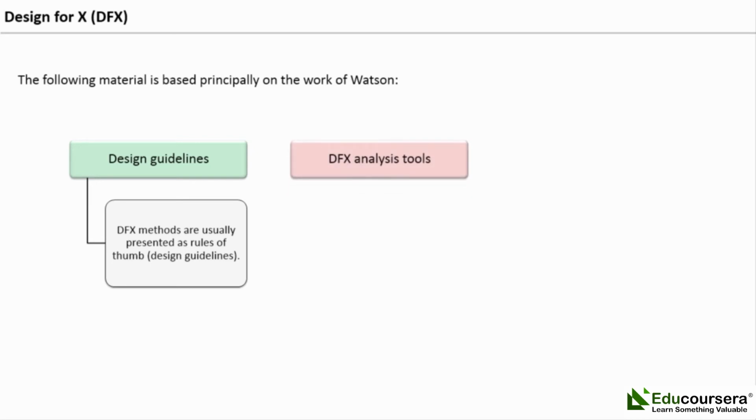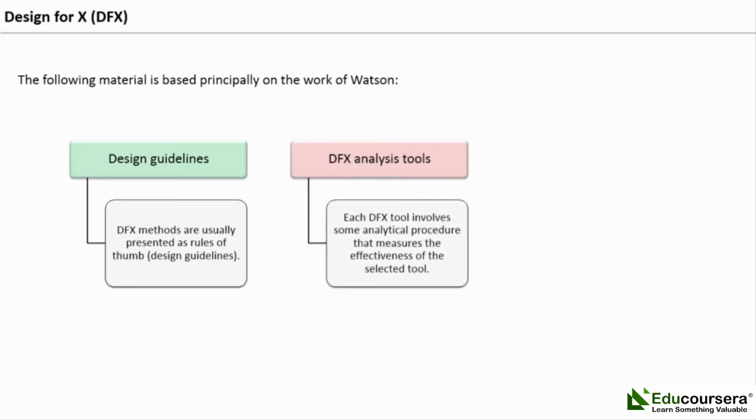DFX analysis tools. Each DFX tool involves some analytical procedure that measures the effectiveness of the selected tool. Boothroyd provides a DFA, Design for Assembly, procedure that addresses the handling time, insertion time, total assembly time, number of parts, and the assembly efficiency. Each tool should have some method of verifying its effectiveness.